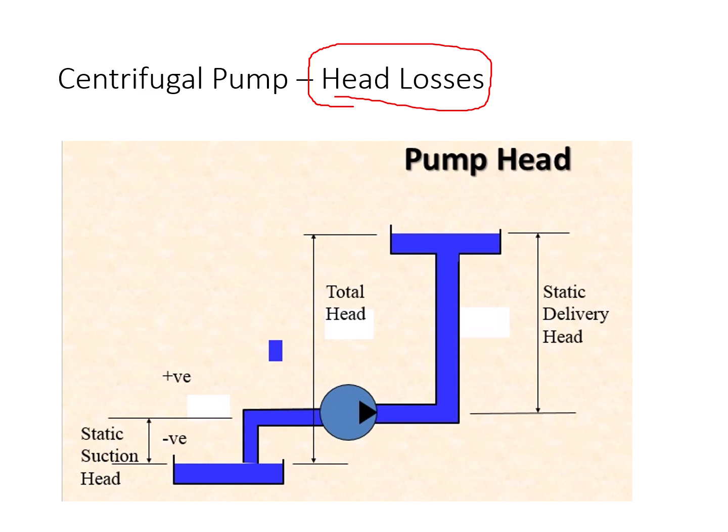You can use, as we just discussed, larger pipes as much as possible to reduce what? The velocity. Because increasing the velocity increases the friction losses. Always try to minimize the number of bends, because many losses happen because of the bends and elbows.